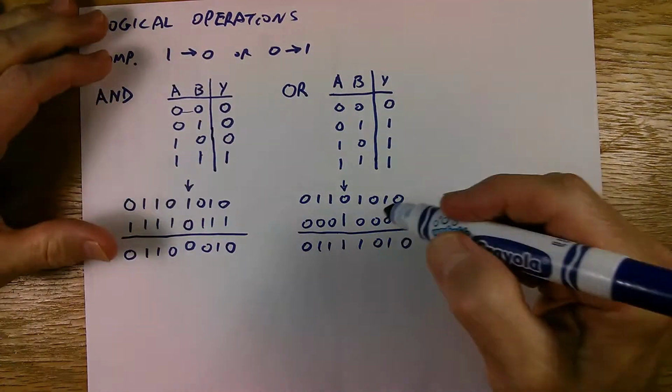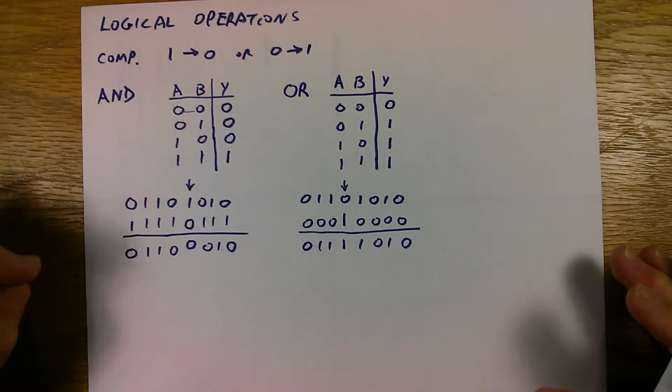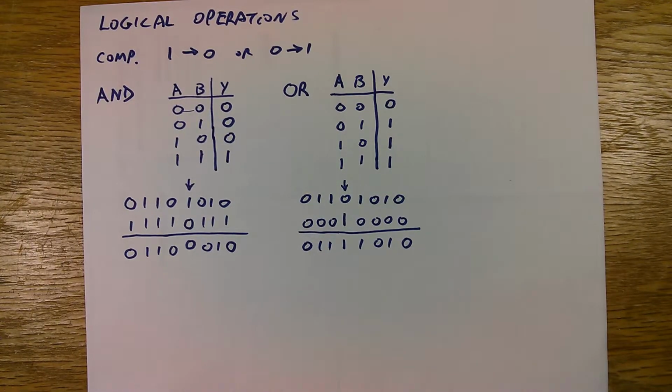Again, you can do it with more than one bit. You just put a 1 wherever the bit you want to be set. So these are useful operations for setting or clearing particular bits in a byte or an int, 2 bytes or whatever. Very useful when you are setting or clearing bits in a control register within the microcontroller.